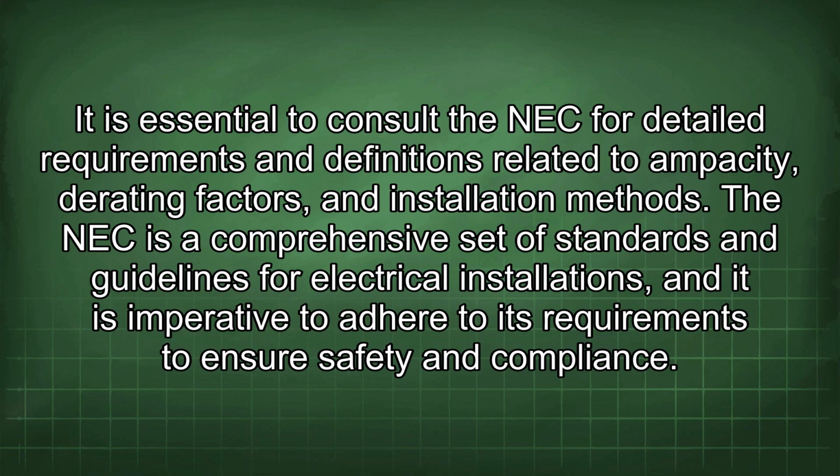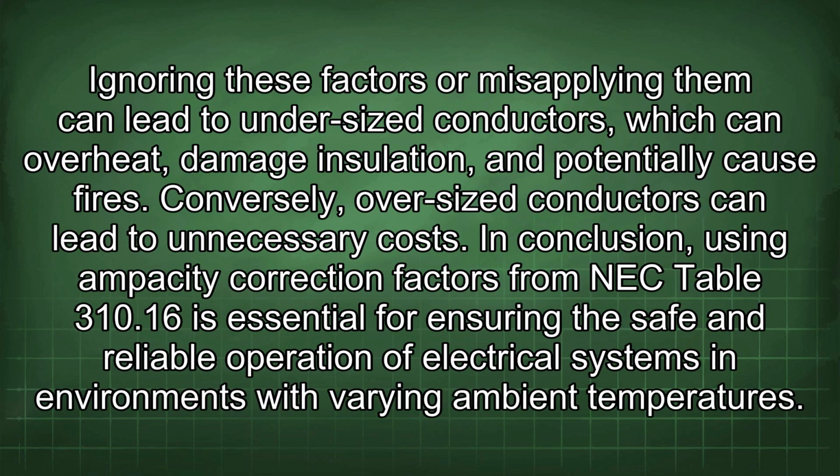It is essential to consult the NEC for detailed requirements and definitions related to ampacity, derating factors, and installation methods. The NEC is a comprehensive set of standards and guidelines for electrical installations, and it is imperative to adhere to its requirements to ensure safety and compliance. Ignoring these factors or misapplying them can lead to undersized conductors, which can overheat, damage insulation, and potentially cause fires. Conversely, oversized conductors can lead to unnecessary costs.